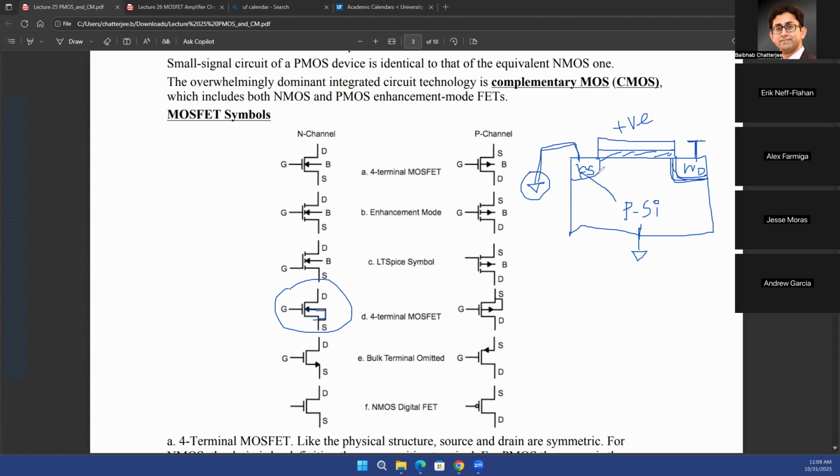The scenario where those PN junction diodes turn on and create a forward bias voltage from the p-type to the n-type silicon is called the body bias effect. If you bias the body at any potential other than ground, you'll see that body bias effect, and there could be a small amount of current flow because of that, which is non-ideal.